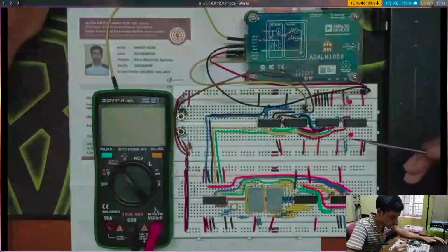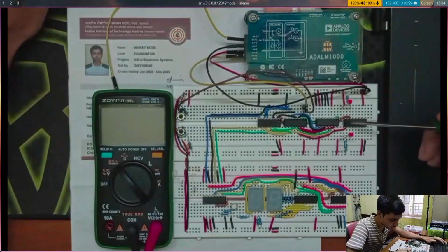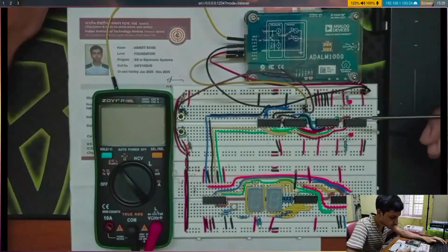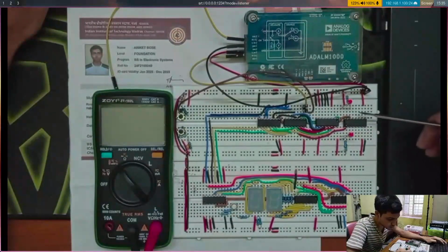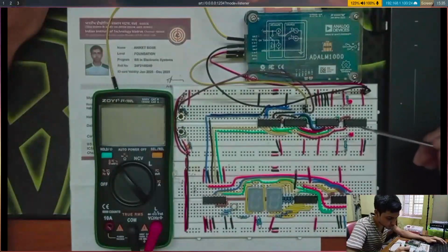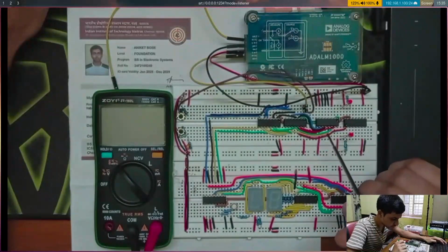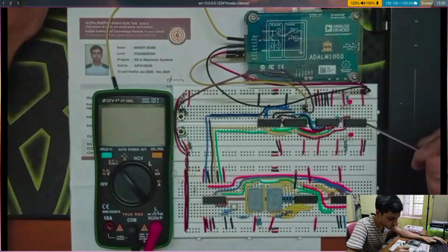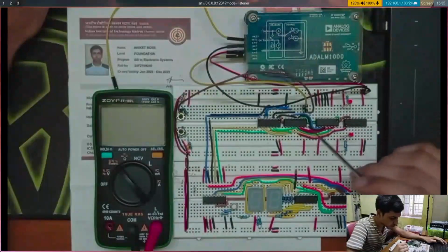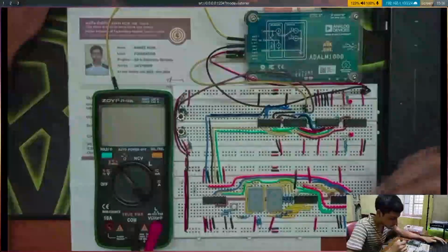So there is logic for the down counting. I have used a quad 2x1 selector and the RCO pin. Whenever the RCO goes 0 to 1, I negate the value to make it go from 1 to 0, which loads 1 inside the counter, and then we negate it to get the proper down counting. And also for the clock of the second counter, so I have used 2 counters here and a selector to do the down counting logic. So one of the counters is used as a flip-flop for the down counting purpose. Using the RCO of the counter, which actually counts upwards, we control the 0th bit to make the number go downwards.